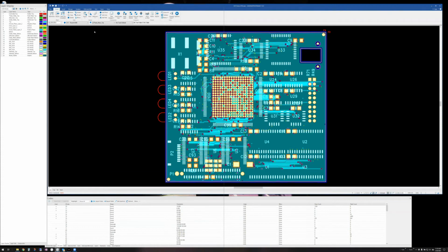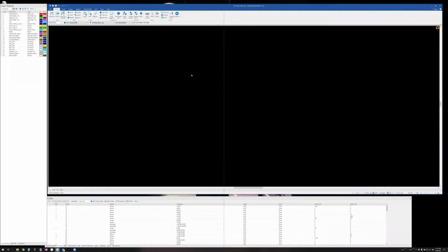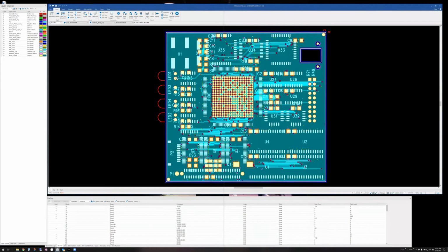Okay, and then writing it out is basically the same. I just turn around and export, and again, if I brought in Gerber and NC, I could do it, or if I brought in ODB, I could create either ODB or 2581. All those options are available to me. Okay, so that's importing and exporting of quote-unquote intelligent data.